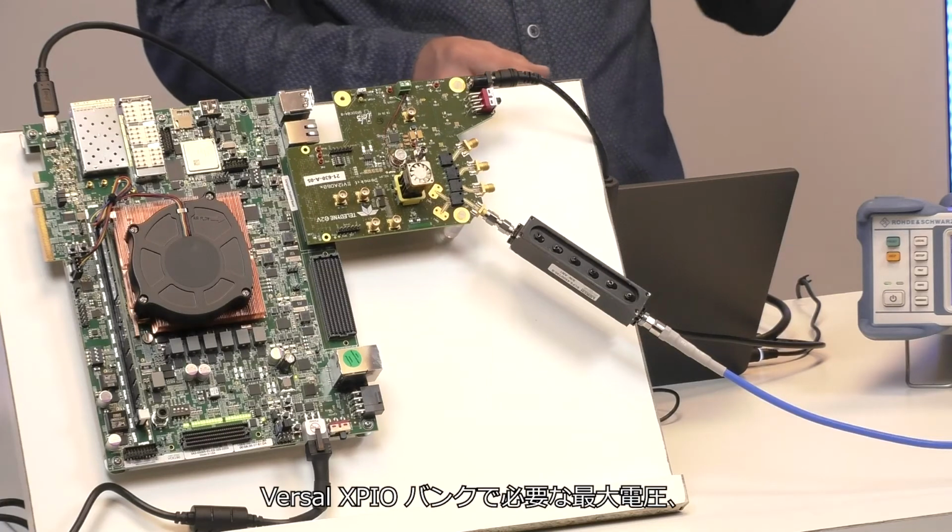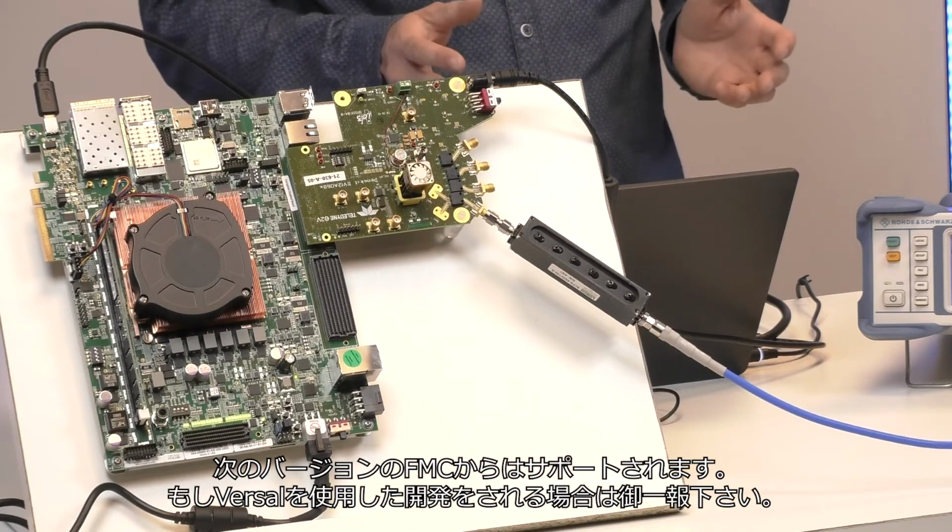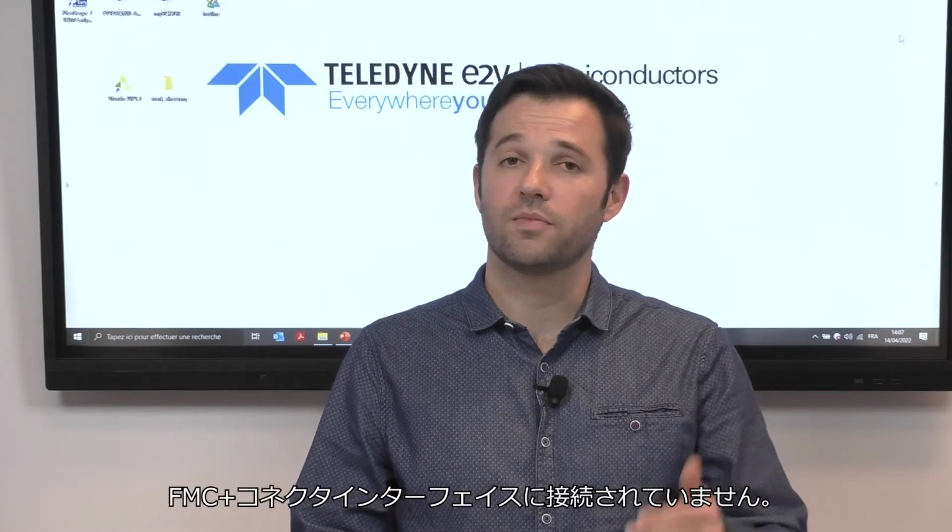I have to let you know that I'm using a modified version of the FMC AQ600 board hardware, as it does not support the maximum voltage of 1.5 volts required by Versal XP I/O banks. HD I/O banks directly compatible with the ADC AQ600 are also available to directly connect the control signals, but these banks are not available on the FMC Plus connector interface. A second revision of the board will be released, so please contact me if you want to order one to start your development on Versal.